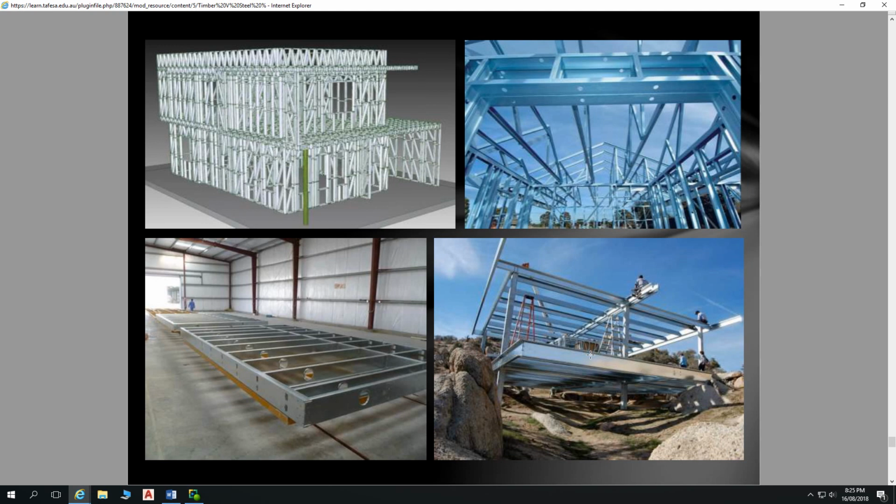And a crane, typically for erecting these very large portal frames, you're paying $500 an hour for that crane. You've got to think about those expenses. That's $5,000 for a 10-hour day, so an hour drive, whatever, 8 hours on, drive back. So $5,000 a day. That adds to the cost, certainly, of such a system. But then also the cost of these members per linear meter, but it enables some fantastic stuff with these large members.